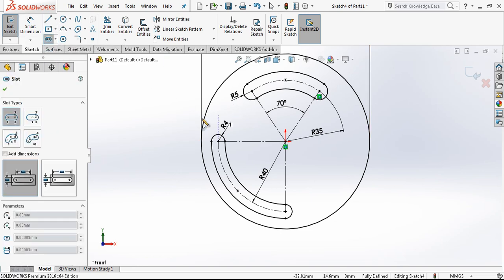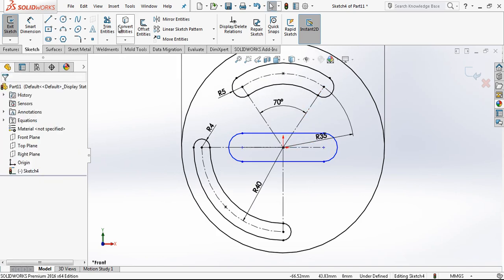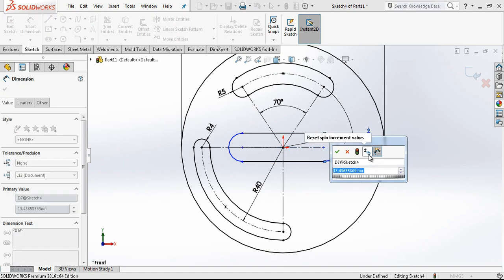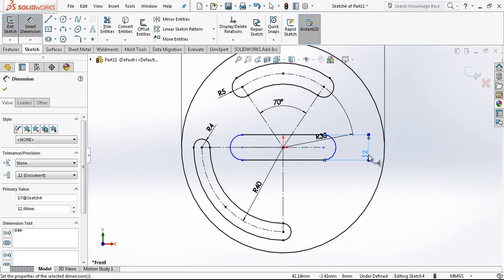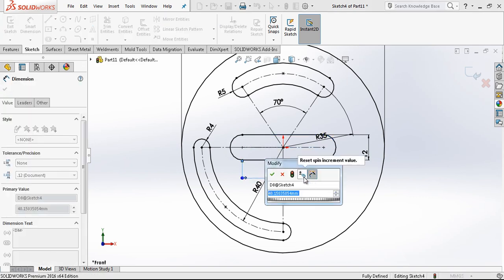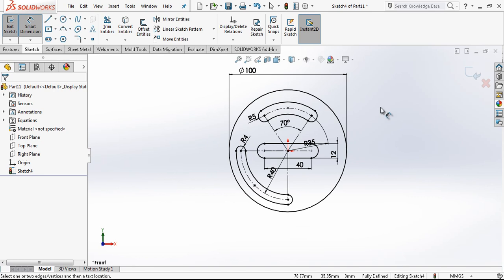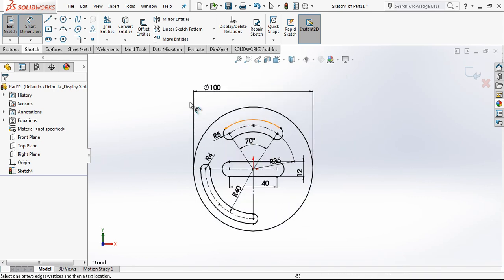The straight slot is a simple one, which is starting from one side of the slot with an ending point, and the same relations again you see here, 1 2 3. The second one is starting from the center. I'm using this much, and you define the dimension. Everything is like a mirrored object. It says it's 12, and when you give this, it is 40. It is now fully defined. It is quite easy to handle with that.